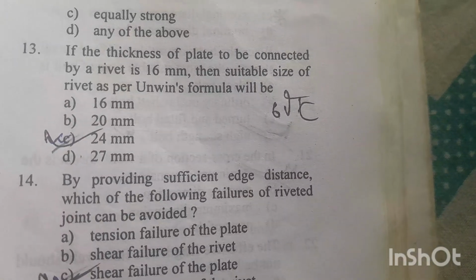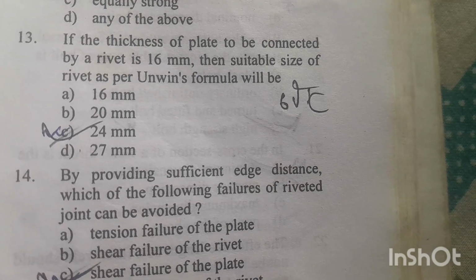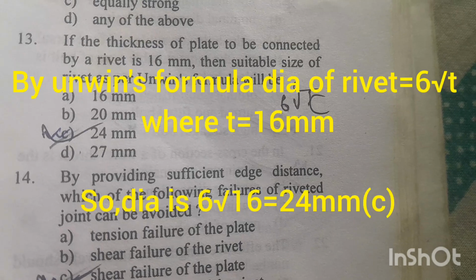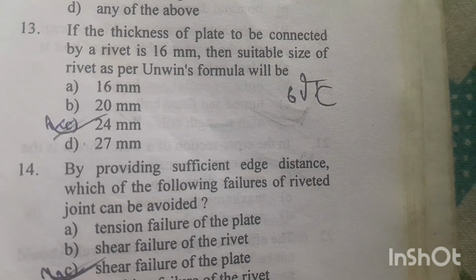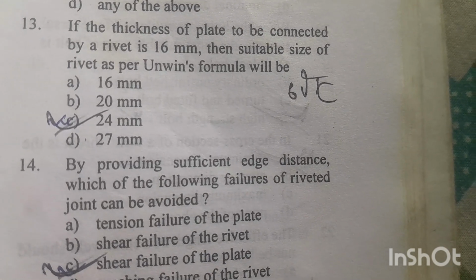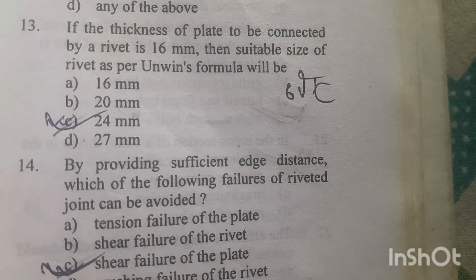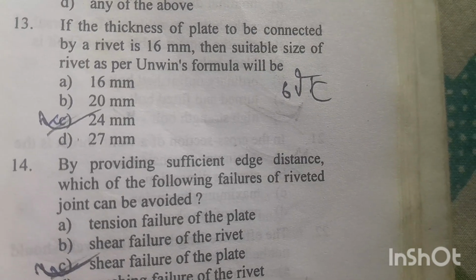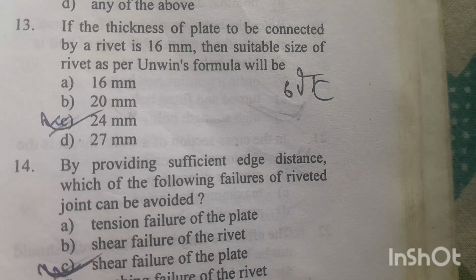Question number 13. If the thickness of the plate to be connected by a rivet is 16 mm, then the suitable size of the rivet as per Unwin's formula will be. We know the formula by Unwin's: the size of the rivet is equal to 6 into root over t, where t is the thickness of the plate to be connected by the rivet, that is 16 mm. So if we put the value, the diameter of the rivet will be 6 into root over of 16, that means 6 into 4 equal to 24 mm. Option C is right answer.